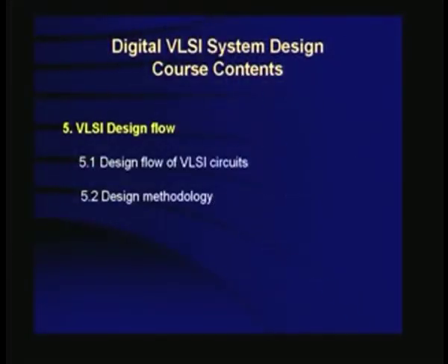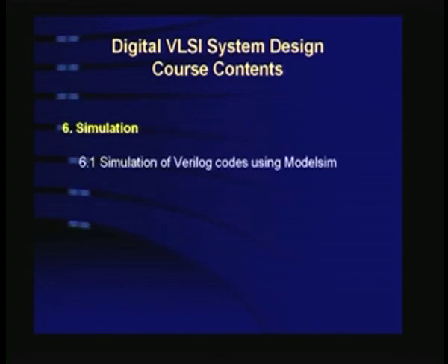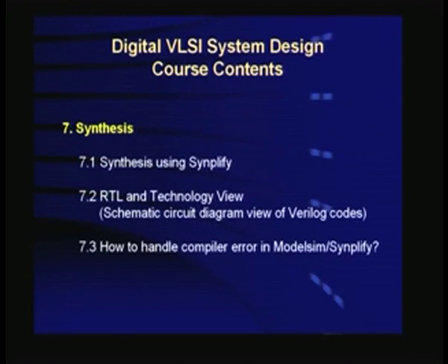So you should know what the design flow is and what the methodology is. That will be introduced to you, the design flow, and then we will simulate. First of all, you will have to simulate it before you plunge into the fabrication. So for simulation of Verilog, there is a tool called ModelSim, which will be used along with Verilog, and we will tell you how to use it. And then you have to synthesize it.